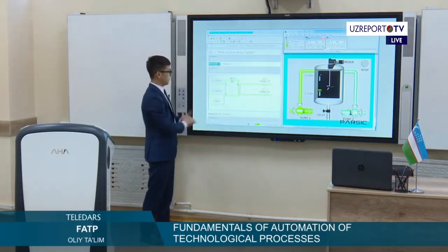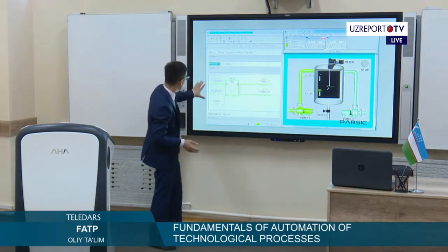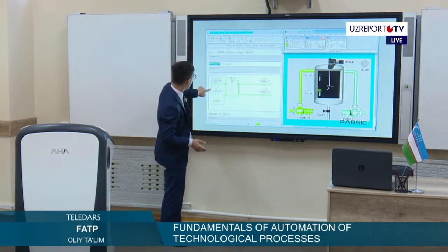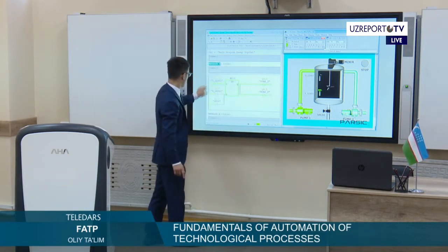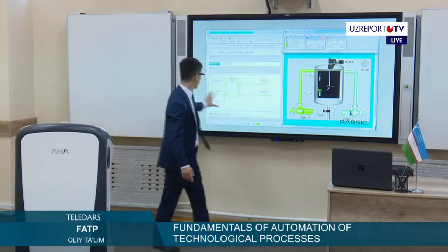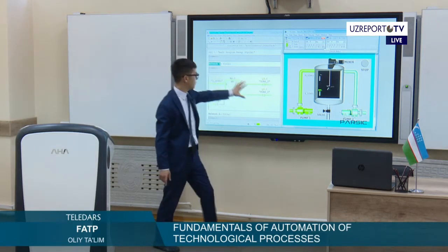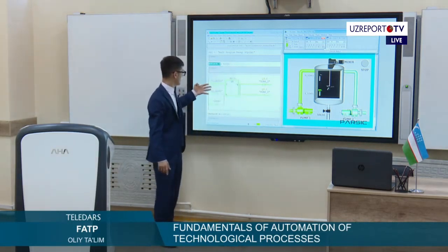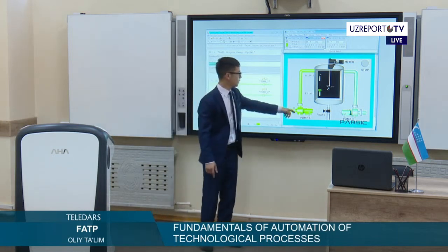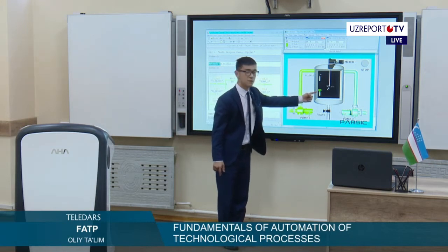And then here is a little model, the whole box where it works. First, we have high and low level inputs, and a stop push button. They come to the set reset block number M0, and this command goes to pump number 1 and pump number 2. When the signal comes from these connections, pump number 1 will start to work when the low level sensor gives a signal.